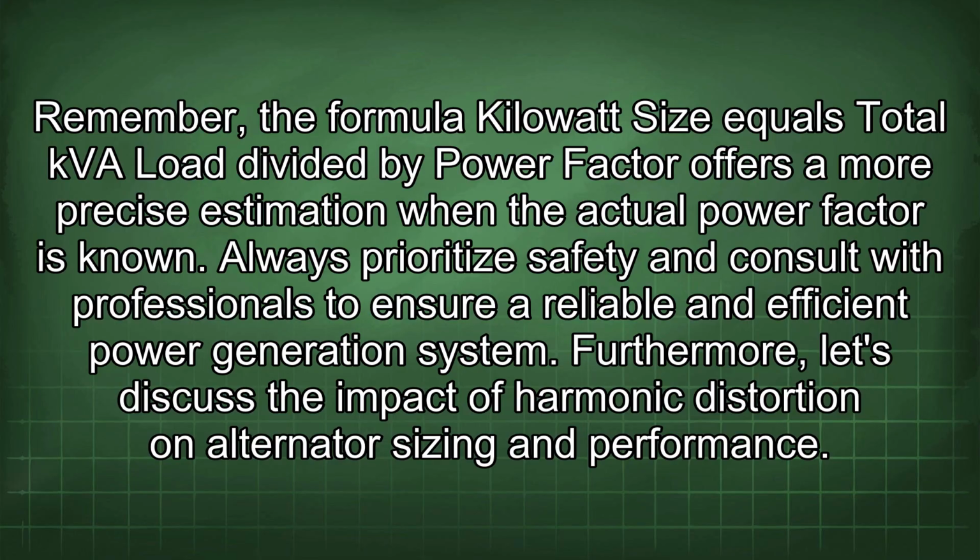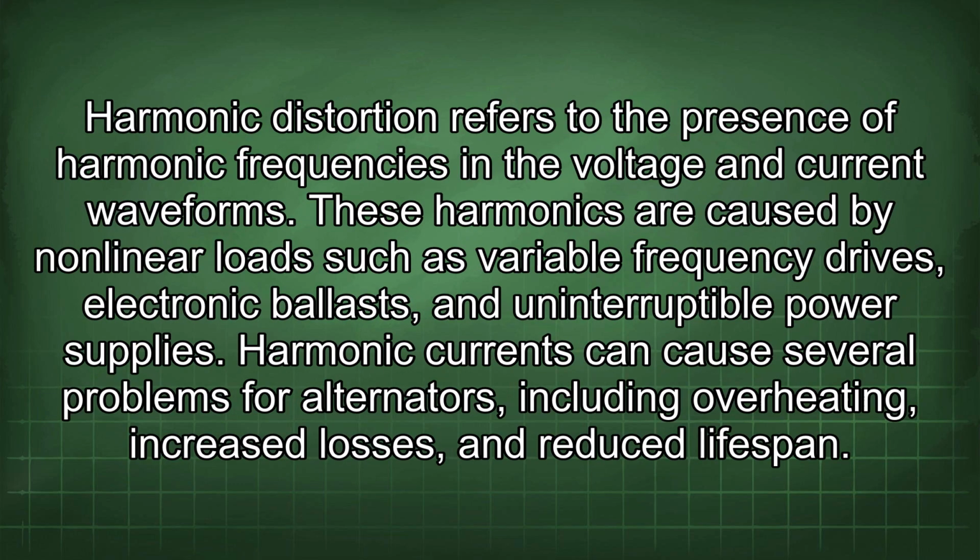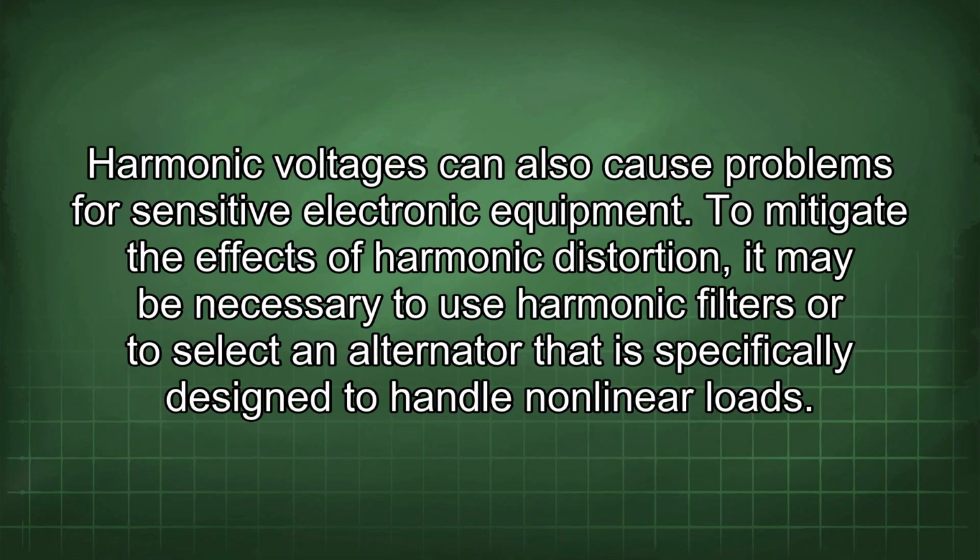Furthermore, let's discuss the impact of harmonic distortion on alternator sizing and performance. Harmonic distortion refers to the presence of harmonic frequencies in the voltage and current waveforms. These harmonics are caused by nonlinear loads such as variable frequency drives, electronic ballasts, and uninterruptible power supplies. Harmonic currents can cause several problems for alternators, including overheating, increased losses, and reduced lifespan. Harmonic voltages can also cause problems for sensitive electronic equipment.